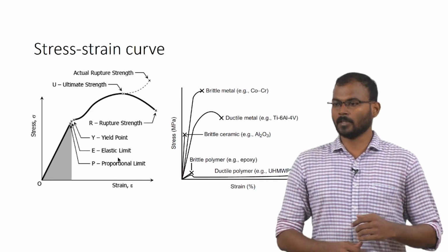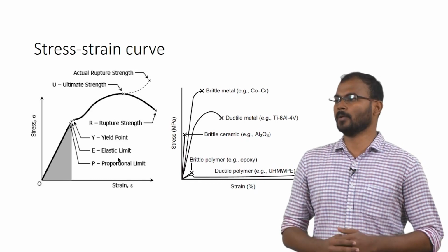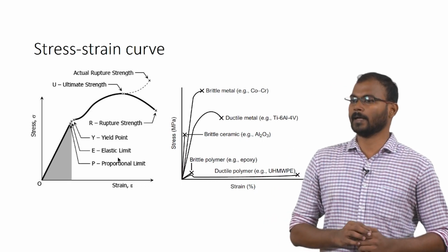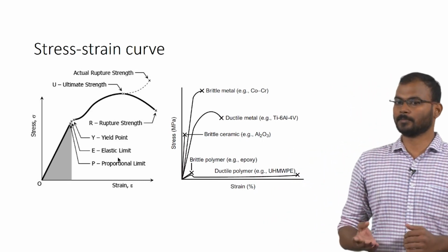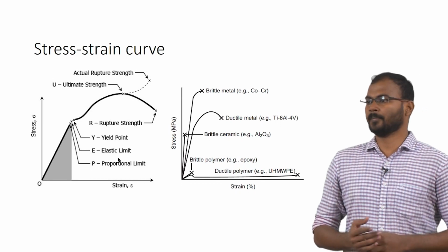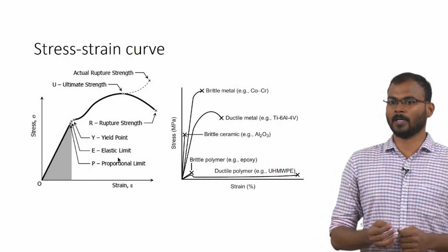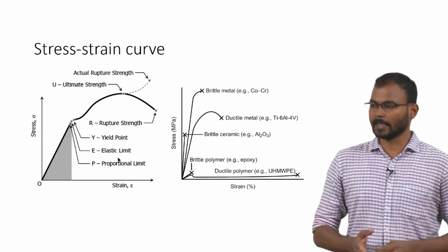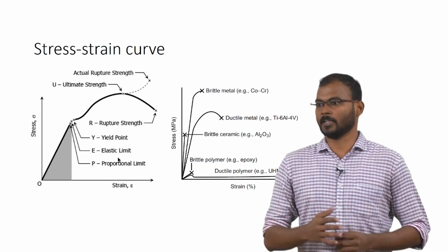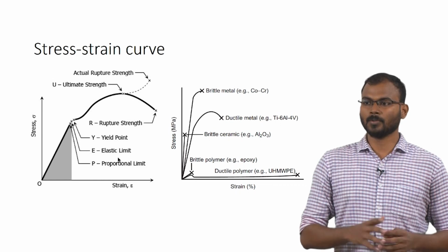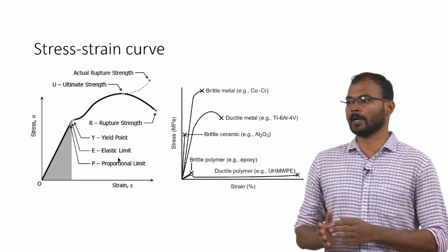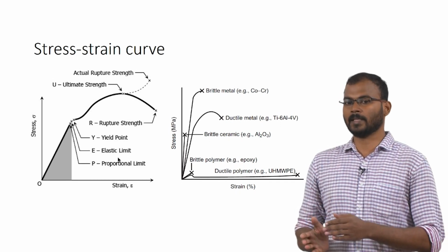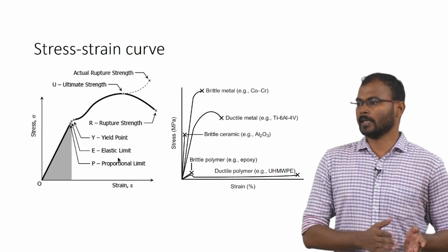Then ductile polymers or other low density polymers, polyethylene, and carbohydrate polymers, all those materials will have a higher range of elasticity, such as PVA, chitosan, polyethylene. Take normal plastic polyethylene. If you extend it, it can go to a very long length. So, those polymers will have a different Young's modulus and different plasticity region. Based on this, and the application you are going to use, you have to decide the material and characterize whether these materials have the same properties as the naturally occurring material.